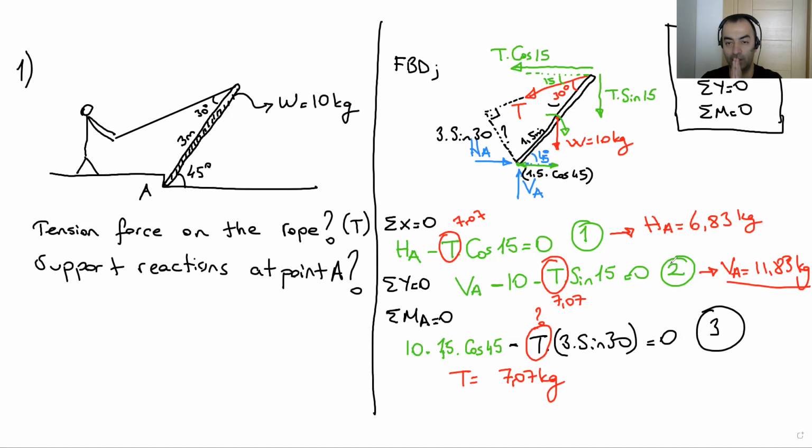Basically, what we did here, we first drew a free body diagram to see all the forces on a sketch. After that, we had an inclined force. We don't like to use inclined forces; we generally resolve them into perpendicular components.